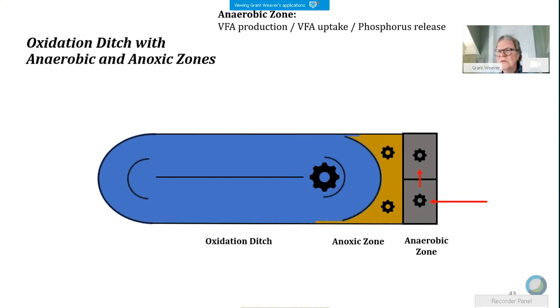So a great process control tool would be to monitor the phosphorus release from that zone. If that zone is not releasing phosphorus, if it's not anaerobic enough, then turn off the mixers. Perhaps have 2 mixers. I would start with running one of the mixers on one day for a period of 24 hours, turn that off, and run the other mixer for 24 hours.